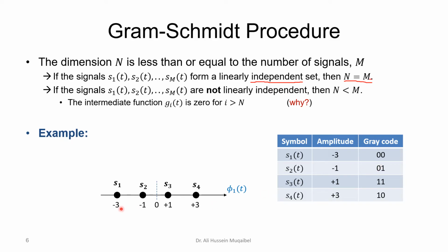And usually we use Gray coding, where we represent the bits, for example, as 0 0, then 0 1, and then 1 1. We don't go in binary order, because otherwise, if you say this is 1 0, then a mistake here will result in 2 bits in error. So when we go to the next closest item, we try to make sure there is a minimum difference of bits. If you say 0 1 and 1 1, that guarantees we have only one bit change at a time. That's called Gray coding. I'm sure you have seen this before. I'm just recalling; if you are not sure, you can search for Gray coding.